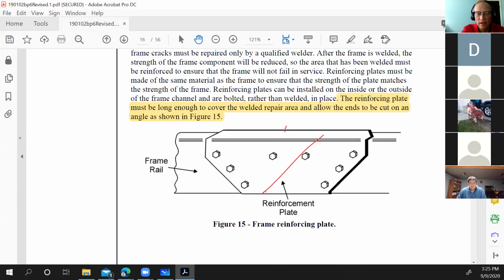So now any load applied to this specific length of the frame is transferred a longer distance, and it isn't ever concentrated on the entire length of the break, okay? You can see here it's concentrated over just this one little portion of the break. The rest of it is all solid, and it's distributed over a larger area.